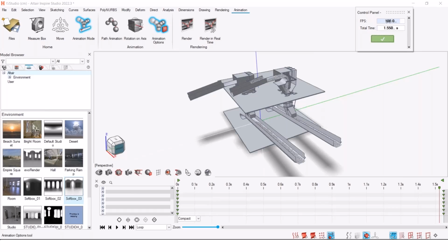It's generally not necessary. Generally speaking, 20 to 30 frames will be more than enough. In cases like this for animation, even 12 can do it. And it will also be faster to render because what you're rendering is each frame. So the more frames you have to render, because of a longer period of time or because there's more frames per second, the longer your render will take to finish.